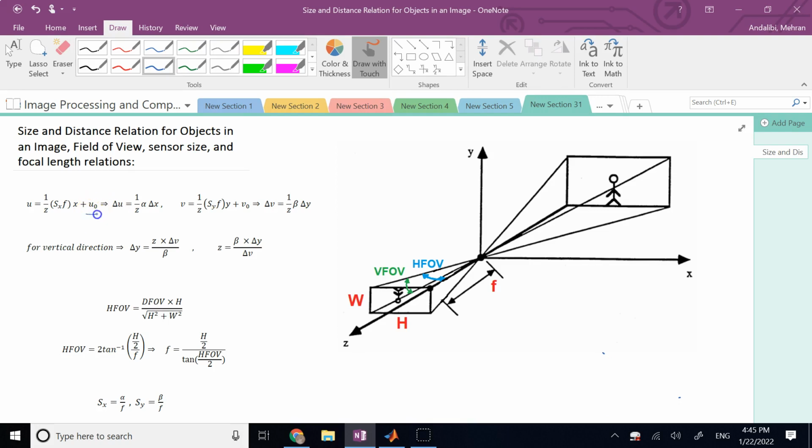In the image plane or camera CCD basically, and f was the focal point, sx and sy were the number of pixels per millimeter of the sensor in horizontal and vertical directions, z was the depth, and the product of sxf and syf, we call them alpha and beta.